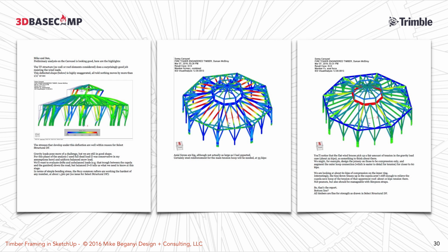And this is just the frame only, so we didn't even count any lateral resistance we get from the walls or any steel connections at the foot bases. So even though that looks like it's going to fall over, the worst case deflection under the worst wind load they threw at it was 1/4 inch. So the thing wants to spin 1/4 inch out of plumb. So from here, everyone's comfortable that A, we're not going to break it once we build it, and B, we can accurately price the timber,